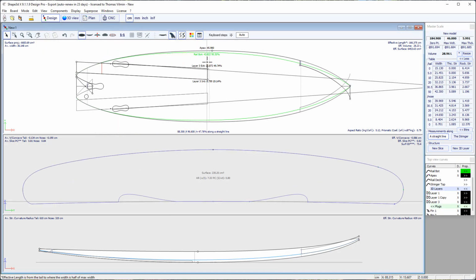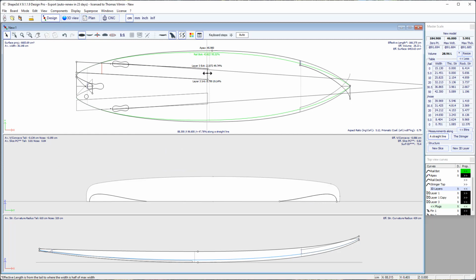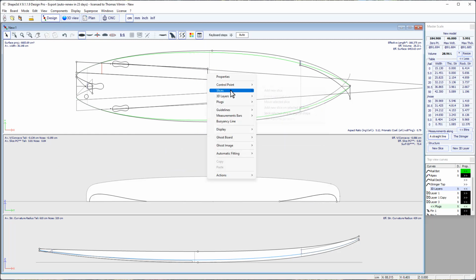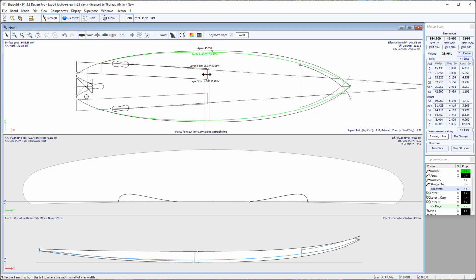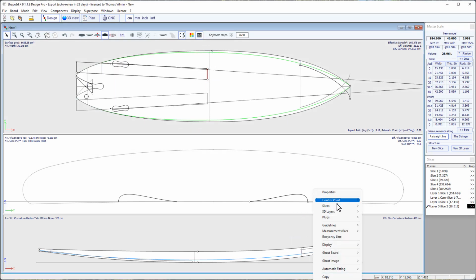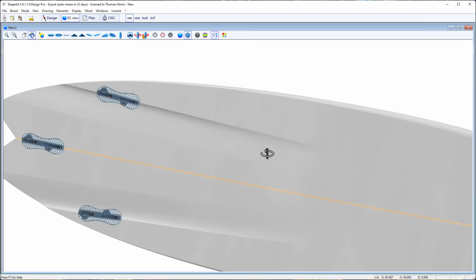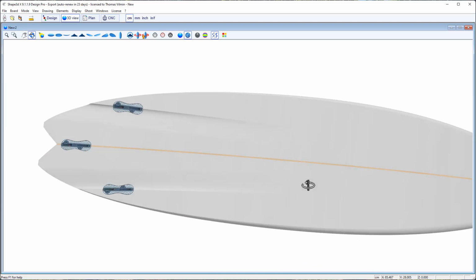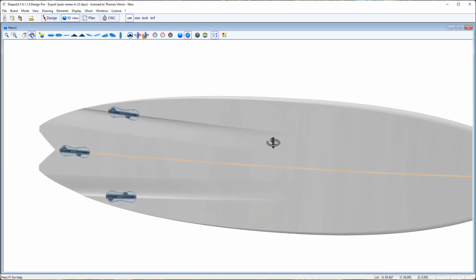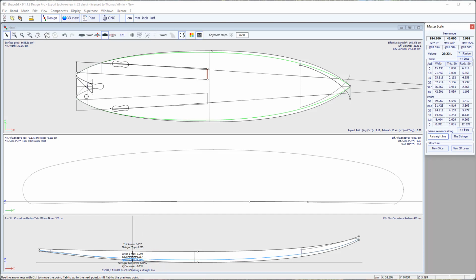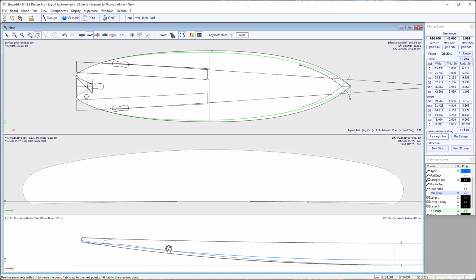Here you want a continuous transition. So what you usually do is add a new slice on the selected 3D layer, and here right click, slice, stick to original shape. And so you have your channel that smoothly merges with the bottom. You can check the depth of your channel here on the side view.